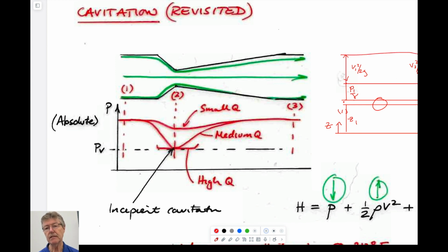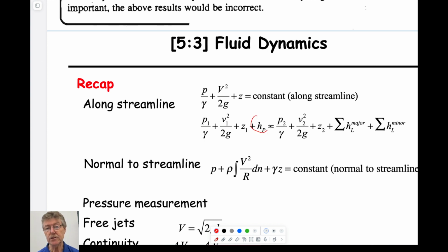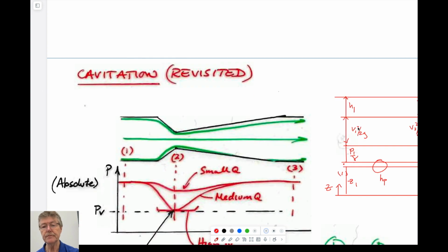And we haven't talked about it yet, but we could imagine that if we're putting energy into the system with a pump, what that represents is a pump head, and head loss. They don't have to be equivalent. So if we go back to this, I'll come back to this. These are the 2 extra terms that we have in Bernoulli that represent energy we're putting into the system and energy we're taking out of the system by the frictional losses as it goes along this pipe.